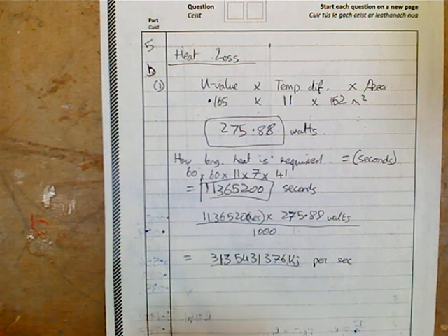Now, as I said to these guys, I know some of you are cutting corners, but I would like you to break it down like this so that you don't make any mistakes, because you were making mistakes in the Christmas exams, and I'd like to avoid that. So now we know how many kilojoules it requires for the year for that wall. Now we need to know how many litres of oil I need to burn to create that amount of kilojoules, and it tells us the kilojoules of 1 litre of oil.